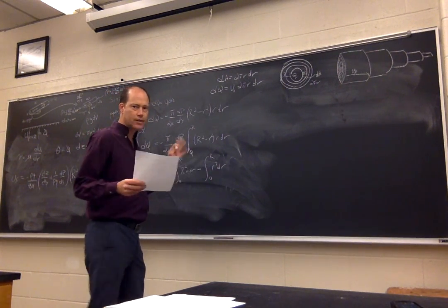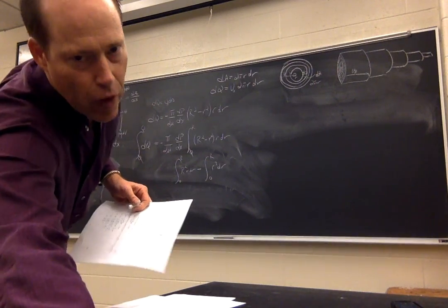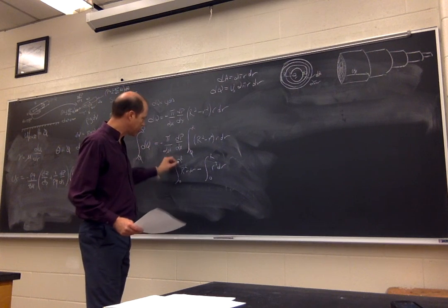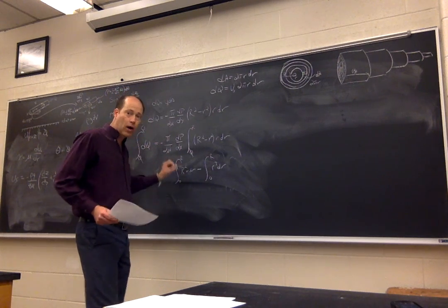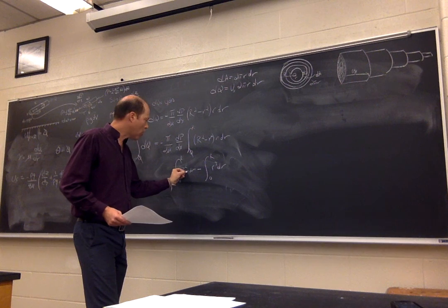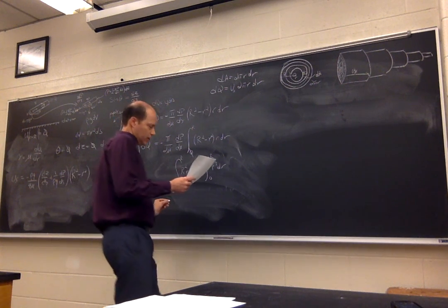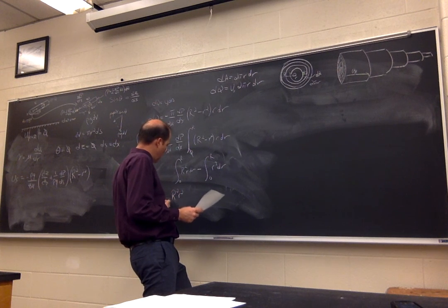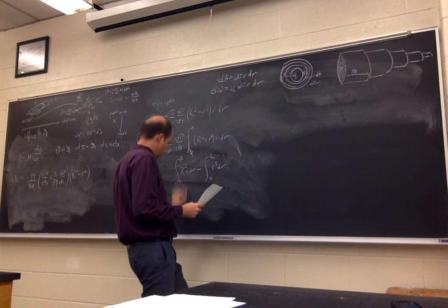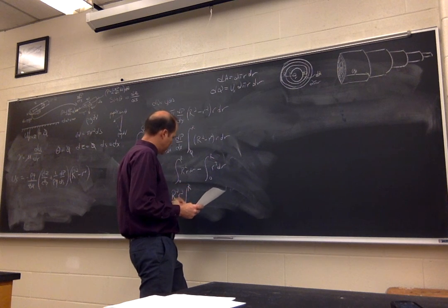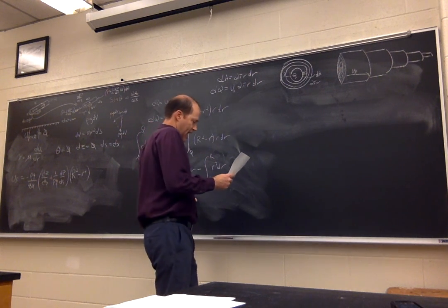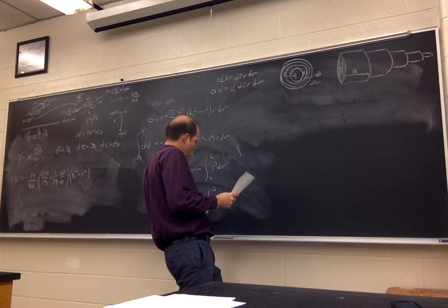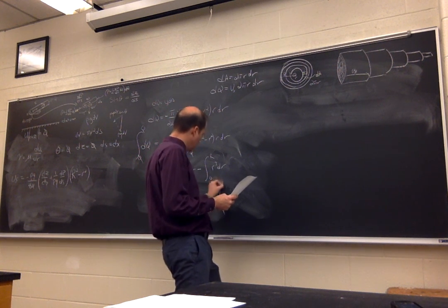Big R is constant in this, remember? Even though we are finding out what the total discharge is, across big R is a constant. So really all we're integrating here is little r. So we have big R squared, little r squared over 2, evaluated from 0 to big R. And then I have over here minus r to the 4th over 4, evaluated from 0 to big R.